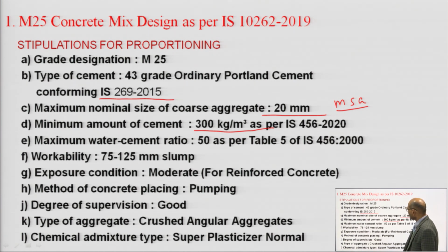Okay. Next is the maximum water cement ratio. This you can get from IS 456, Table number 5, based on the durability requirement and exposure condition.